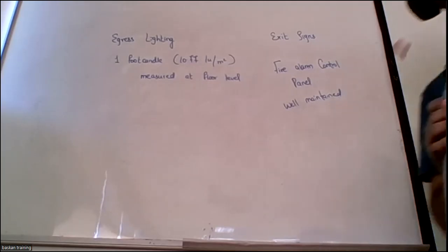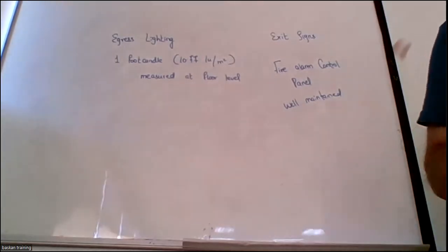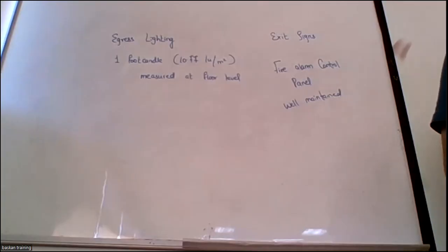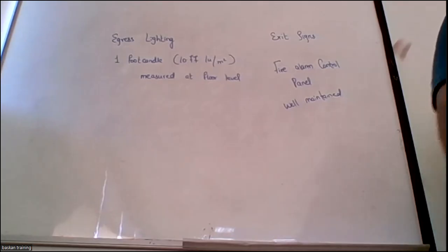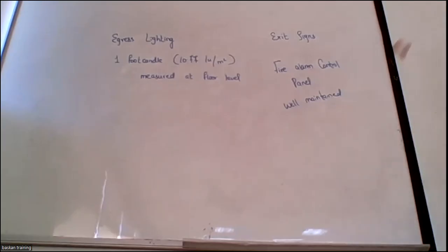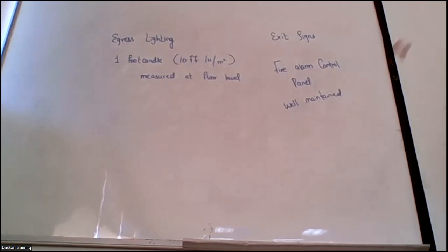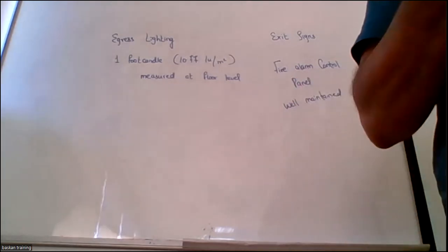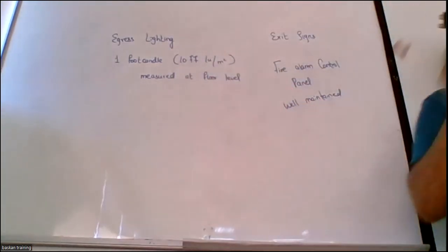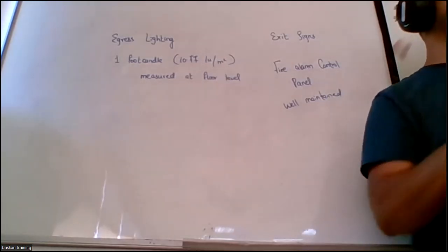Exactly. Secondary power supply. The batteries. Because in case of fire emergency, the first thing that is going to cut off is the authority power, right? So once it's cut off, your whole system will be running on the batteries. No matter how expensive or effective a unit you have, if you don't have a backup, it's zero. Nothing is going to run. Your annunciations, detectors, notifications, everything is dead.